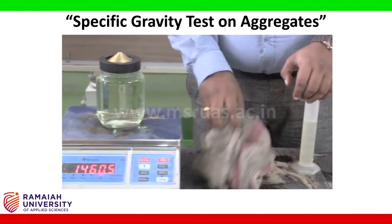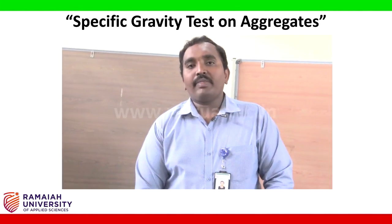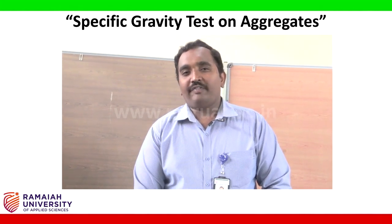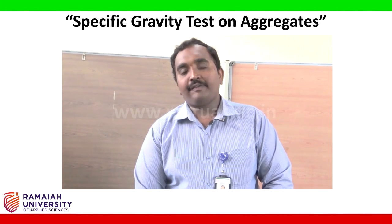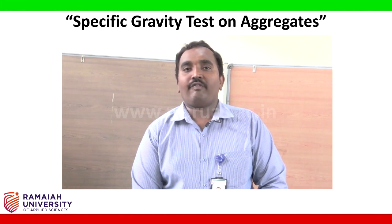By having these 4 weights, we can easily calculate the specific gravity of the fine aggregates. Generally it lies somewhere between 2.5 and 2.6. It depends upon the source of the fine aggregate. This completes the specific gravity of fine aggregates.